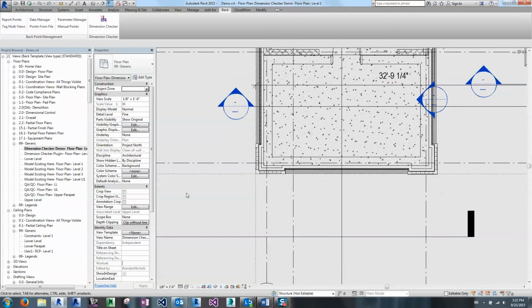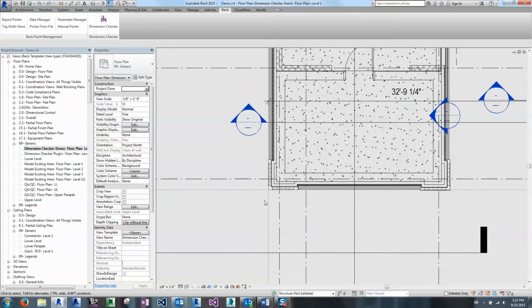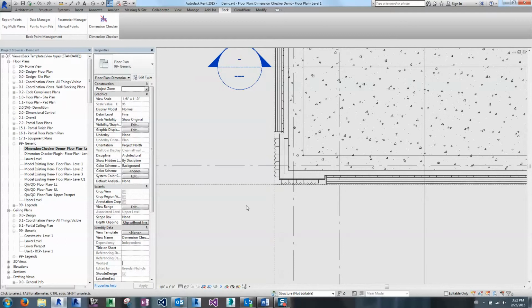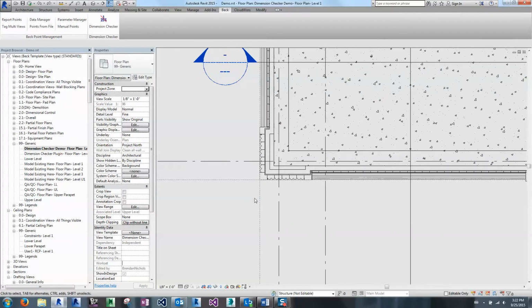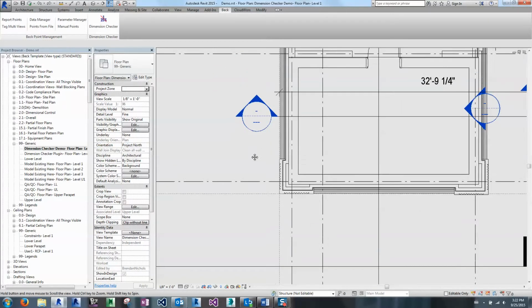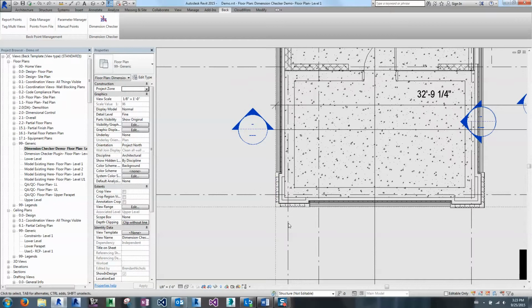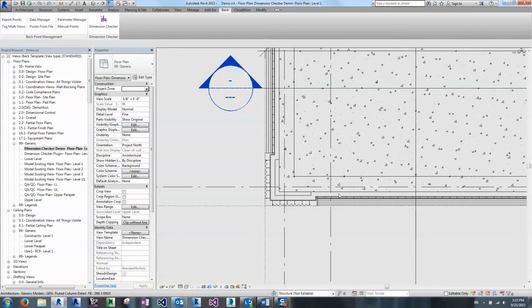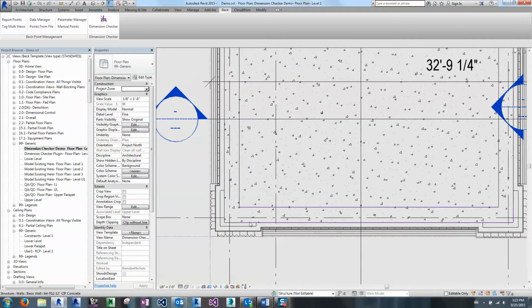So in our template, the Revit project origin is defined or highlighted by these two reference planes that exist. Generally your project base point is going to be here as well, but that can be moved as well. So you need to know where this project base point is and make sure it's at a very useful location. In this case we have it at building corner, but you could also have a grid line intersection or something similar to that.